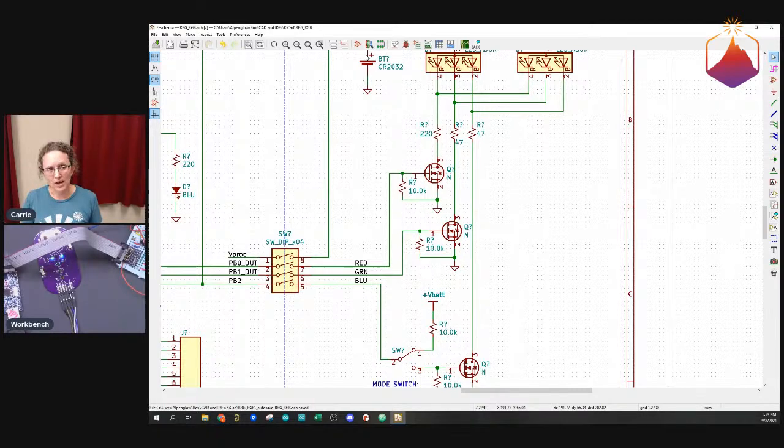If full brightness is full on and off is off, then for 50% brightness, you tell it to be on 50% of the time and off 50% of the time. You just make a square wave that toggles between them many, many times per second. For a quarter brightness, it's 25% on and 75% off. That's the way you do it. You just control the amount of time.